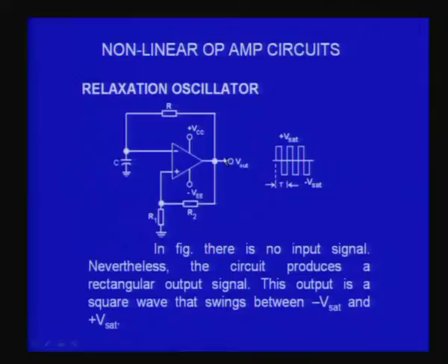So you find therefore without our switching voltages, the output automatically switches between plus Vsat and minus Vsat depending upon the charging of the capacitor or discharging of the capacitor. Whenever this charging and discharging crosses the LTP and the UTP, you get the output shifting from plus Vsat to minus Vsat, etc. So I have also shown you the square wave that we get at the output.